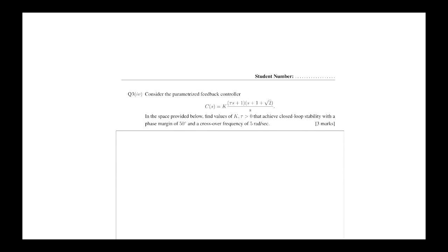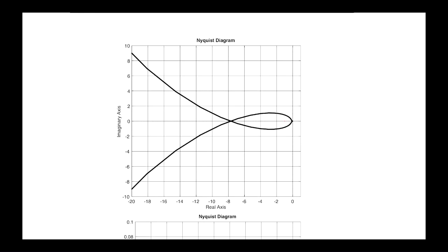So we know that when we have poles at the origin, we've got to go around a little indentation as we're moving around the D contour, and you get minus pi radians change in phase for every pole that you go around with the little indentation, right? So, of course, those things aren't drawn on these plots, right? So to figure out in the end how many encirclements of the critical point you're getting, you're going to have to effectively draw those in, right? So you'll have to do a similar thing this year. Okay, so practice these sorts of questions.